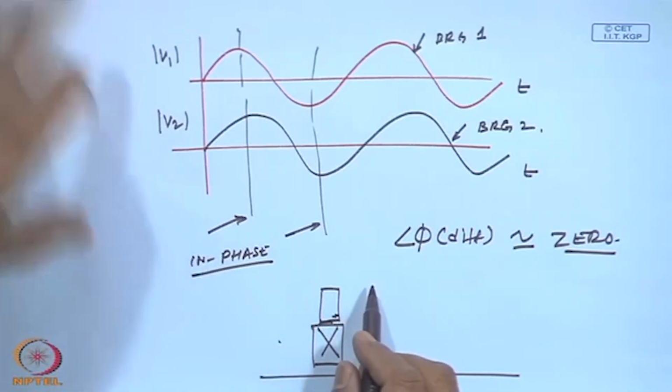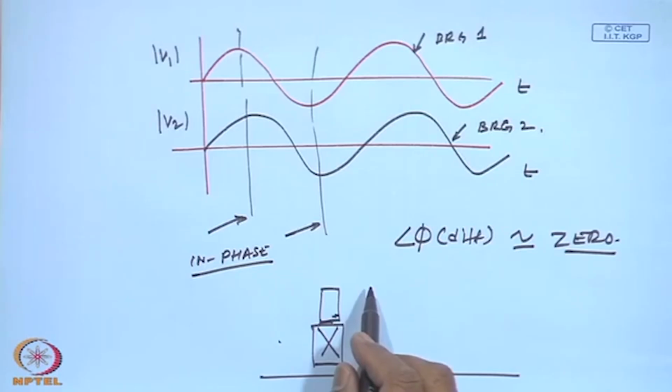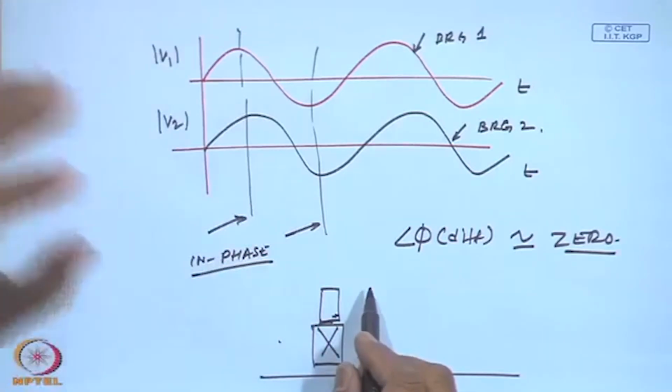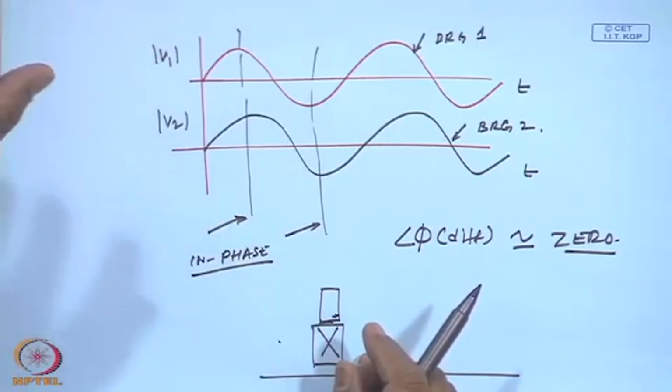So, these are the diagnostic techniques or routines which we have to follow to ensure that it is unbalance and not looseness or misalignment or a cracked shaft. So, these are the processes by which we can be sure that yes, there is an unbalance, because I am having a high radial force or high radial vibration compared to the vibration in the axial direction, and then of course, the vibrations between the two bearings are in phase, or they are at 0 degree.